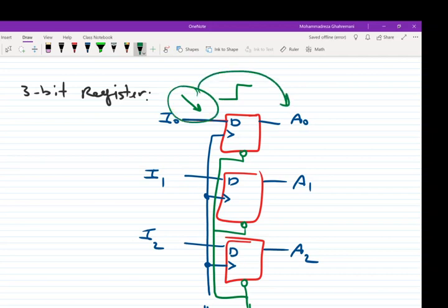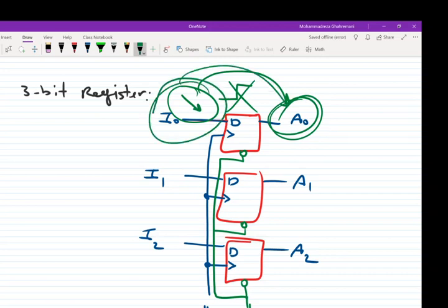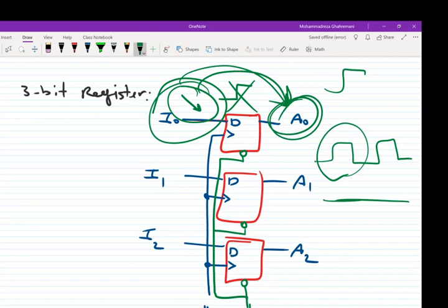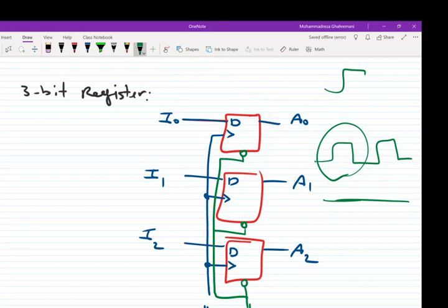The input moves to the output, and if we stop applying more clock cycles, the output will always be constant. The data at the input moves to the output, and it will be stored at that location until the next clock cycle we apply. So we don't have to apply the clock continuously. We can apply 1 clock cycle and then disable the clock signal. By applying one clock signal, the information moves from input to output, and until the next clock cycle, the output is constant.